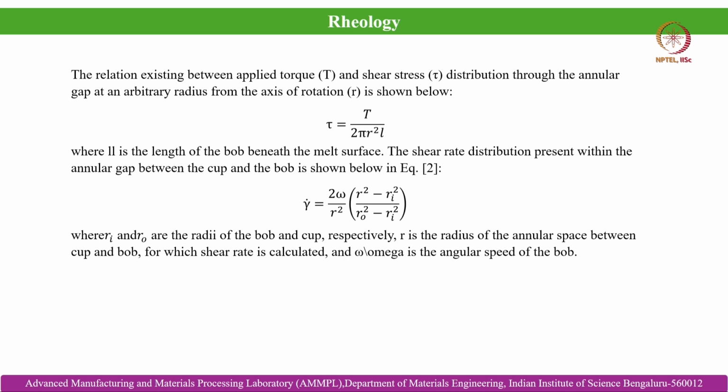Now we will again discuss a case study of rheology that has been done in our group, where we studied the viscous evolution of a solidifying liquid melt within a rotational rheometer, more specifically the Searle type rheometer, where, as I have already told you, the rotational grooved bob is rotating, and the outer cup within which the bob rotates remains stationary. We keep the fluid in the annular space, for which we are measuring the viscous evolution. In this case, it is the solidifying liquid melt.